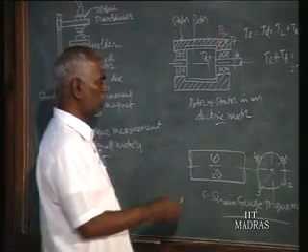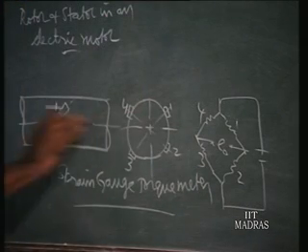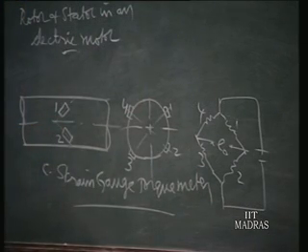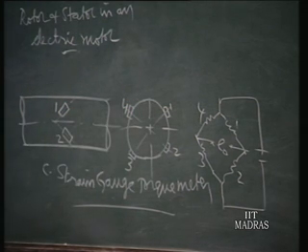Here what we are doing is this is a transmission. This is a shaft taking the torque from the power source to the power sink. In between we fix these strain gauges. As I already told in the force measurement, we have to weaken the place where the strain gauges are pasted, otherwise the signal will not be sufficient.